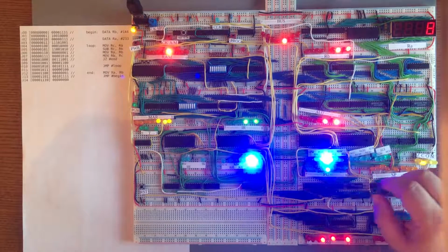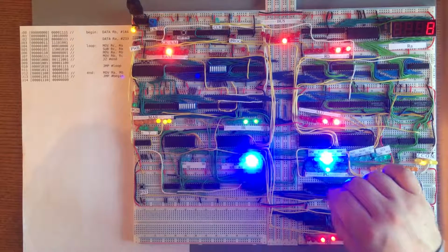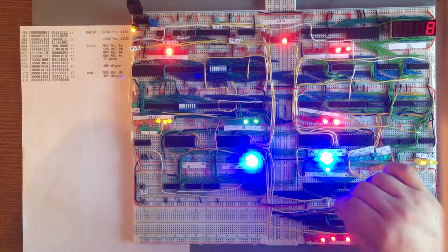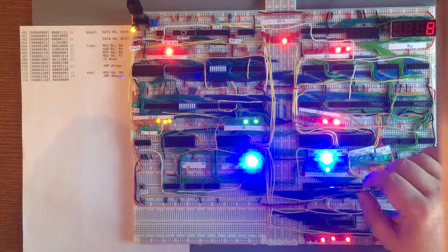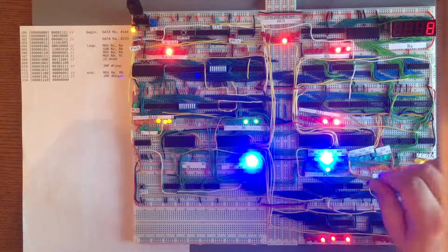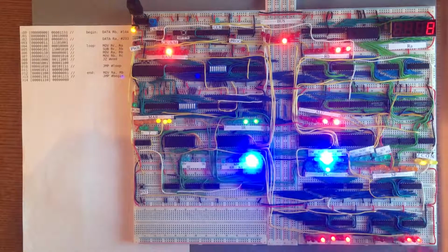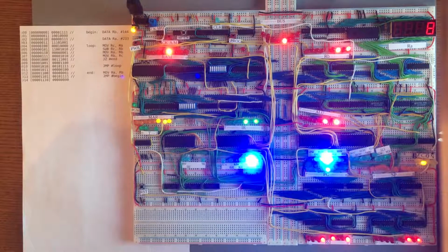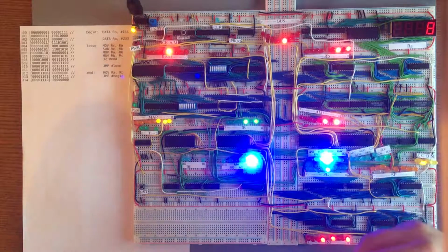That's what we call asserting a value onto the bus. And so any other component which would connect to these 8 wires would find those voltages on the lines. And that's the idea of the bus. The bus is just a set of wires which we can connect and disconnect to the various components of the computer using control signals. That's exactly the whole point of a bus. And so we'll have a look in detail at how that works.